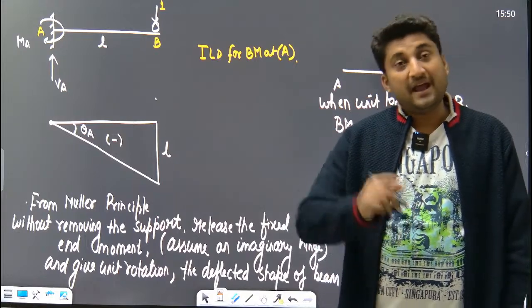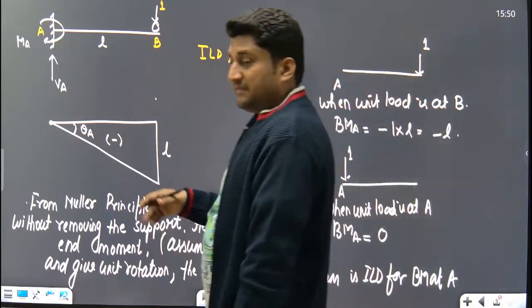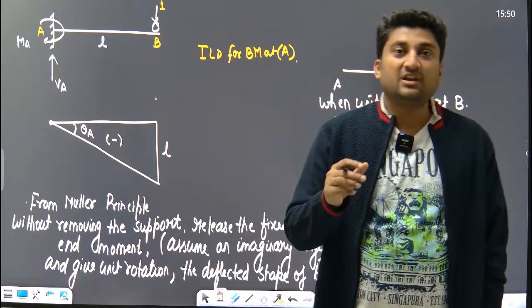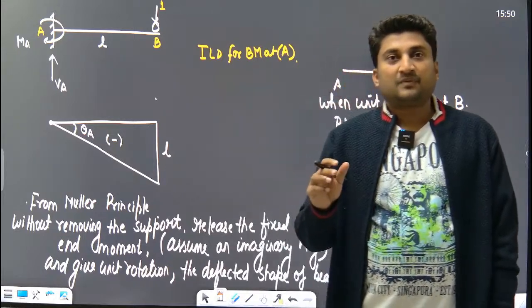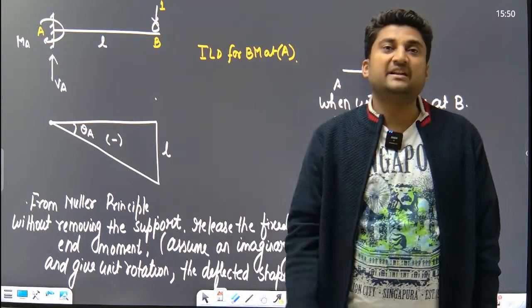Yes or no? And in a simply supported beam, what was the concept? For ILD for reaction, remove the support, give unit displacement. The deflected shape is the ILD for reaction.